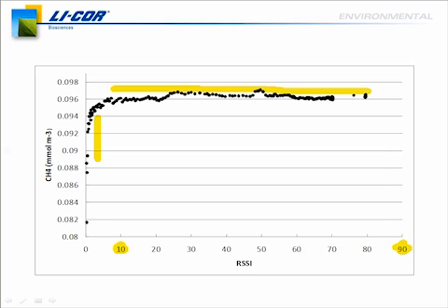So again, depending on how often you have to clean, if you're cleaning the instrument maybe once a day or twice a day, you're going to be able to use that reservoir for quite a few days. You can also attach the pump to an external reservoir. So if you've got a site that's really difficult to get to, and you really don't want to have to get out there very often, or there's just a lot in the air and you have to clean more frequently, you can just attach any liquid reservoir and fill that up and use that as well.